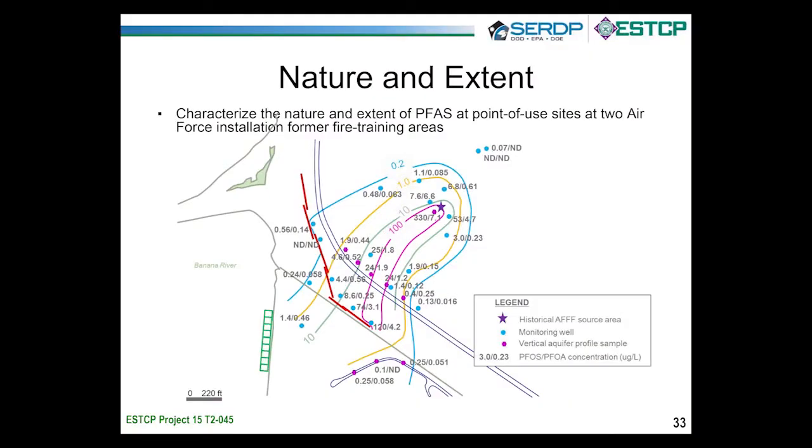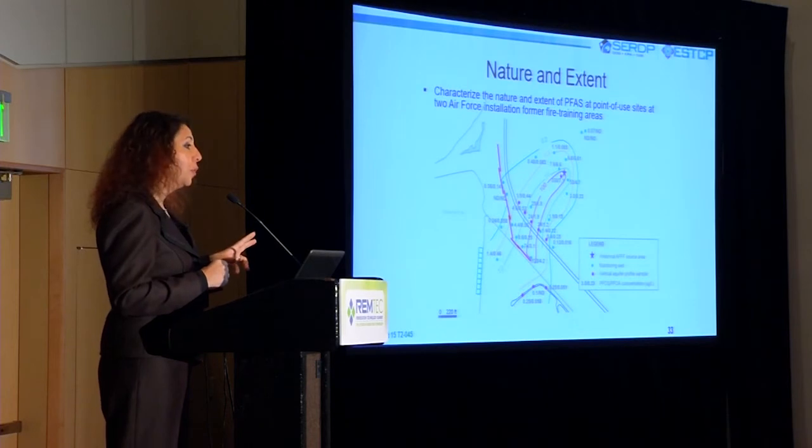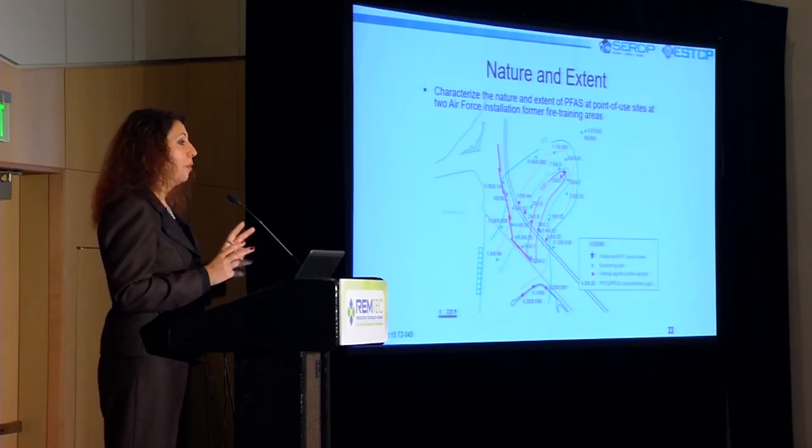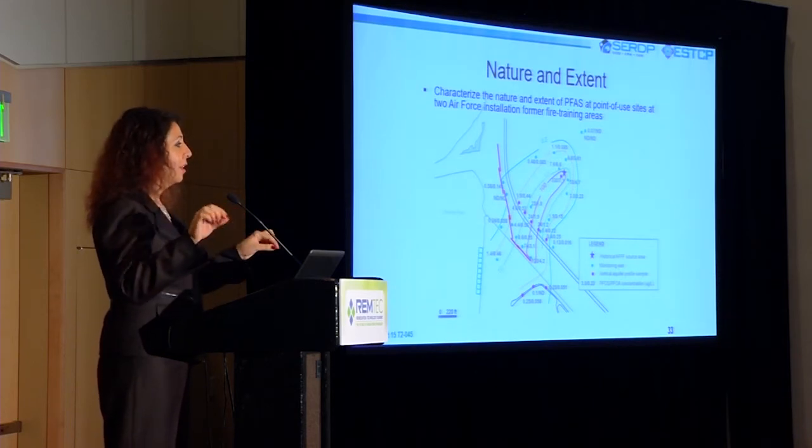This is work or results from Cape Canaveral in Florida. Just a few things that I want to say about this figure. One, the nature and extent of contamination, we were able to get to it after 3 mobilizations. So because there were very few existing monitoring wells, we had to put in temporary wells and kind of poke the holes in the ground, see what the results are, wait for the results to come back, and then either widen our area of interest or shrink it, which is why it required 3 mobilizations.